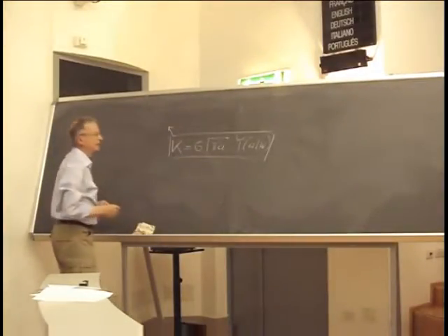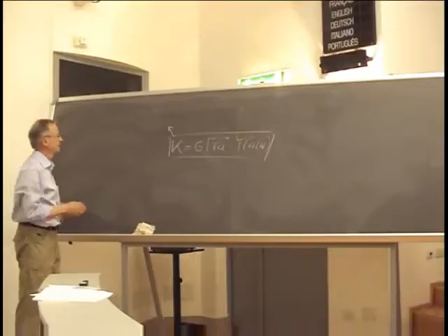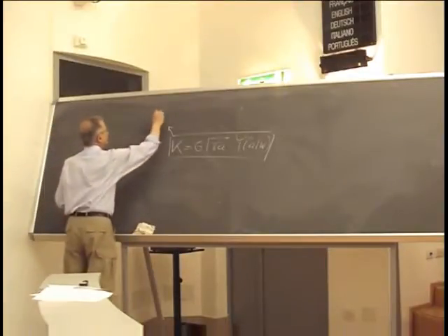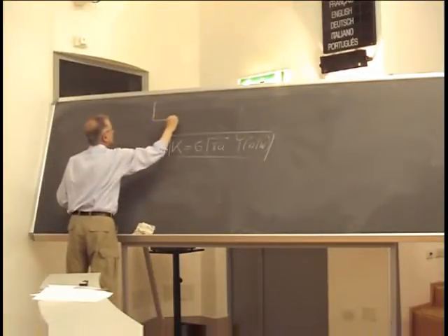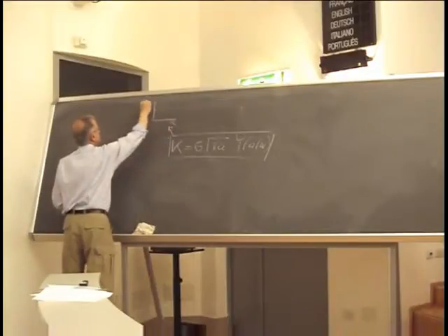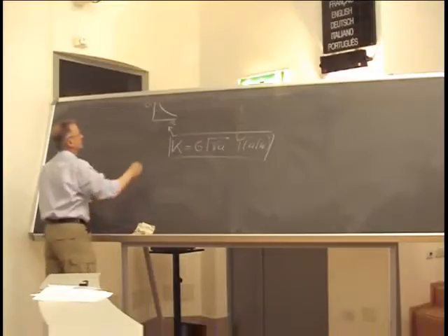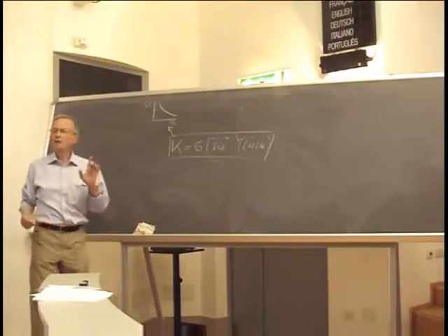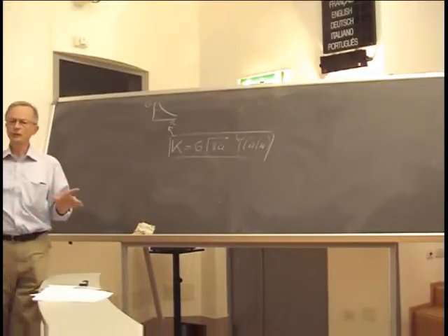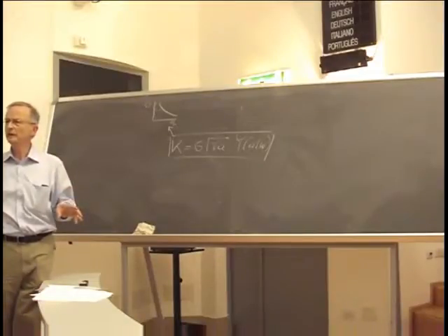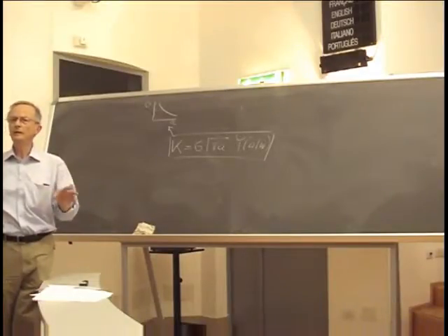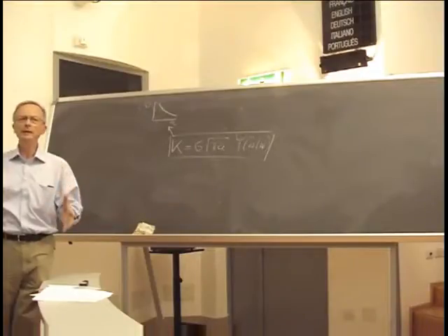You may remember that on Monday I told you that it is important, here's a prediction, to have a look at the yield force, yield moment, or whatever it is, because you can't use linear elastic fracture mechanics beyond yield.